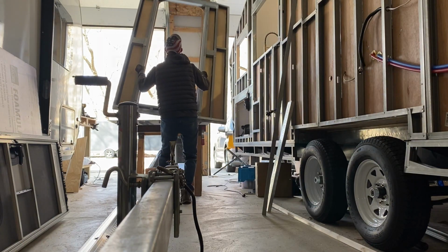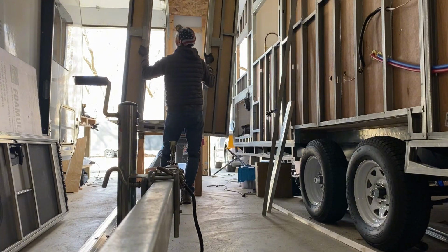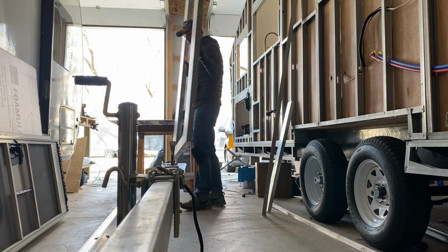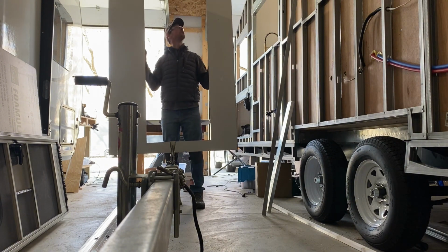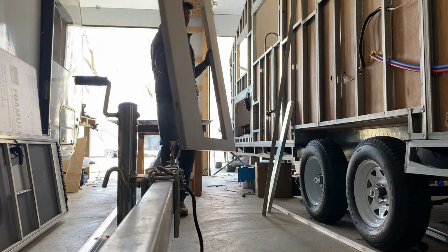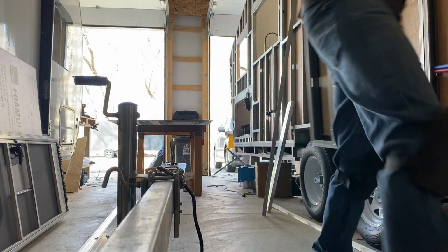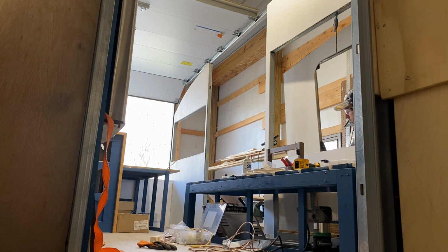Another feature for the construction on this is it's kind of a twin wall construction. Again, borrowed that from my home that I live in. Has framing with insulation on the inside and then continuous insulation on the outside. Usually that's nailed on. This is actually glued on, which was a learning curve, but I came up with some pretty cool processes to make that work. And what it allows for is reduced thermal bridging from your outside temperatures on the inside.